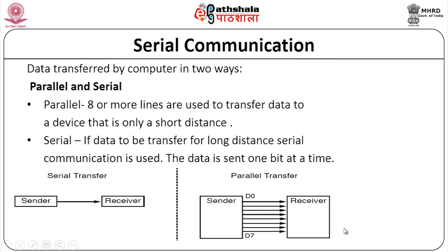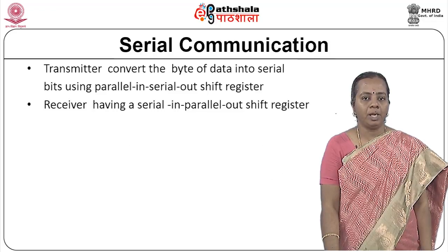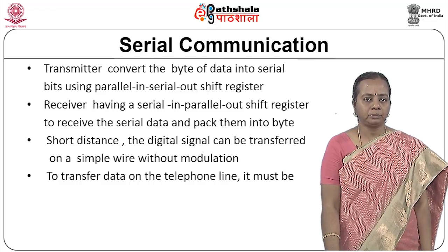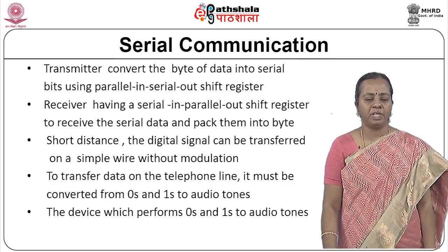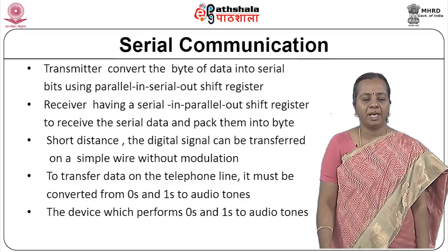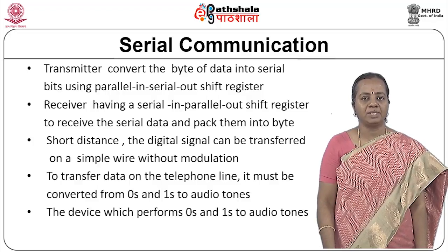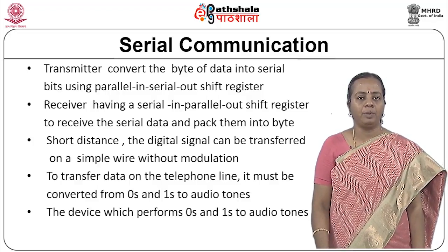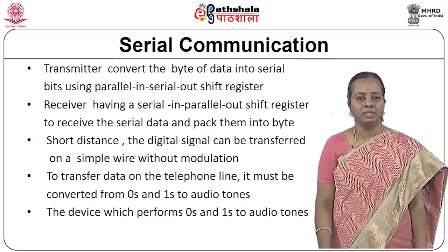Serial communication has its own advantages and disadvantages. If I want to send fast, then people will go for parallel communication, but it needs more bandwidth also. In serial communication, I will be sending data bitwise, one bit after another. But the data is given as a single word, that means 1 byte or 2 bytes.